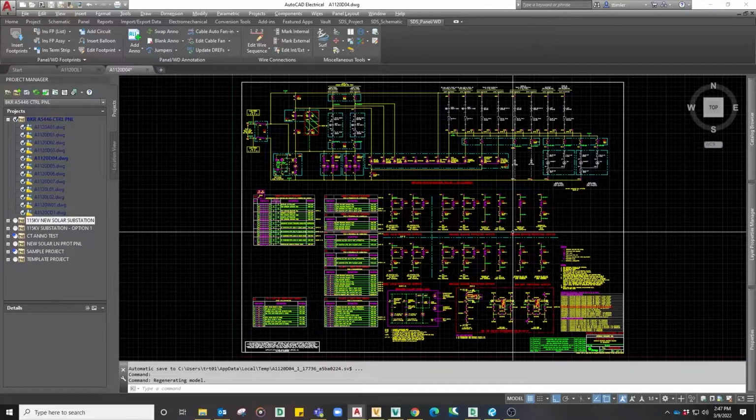All of these pre-wired protection outputs contain the master symbols that are used in conjunction with the SDS ref-only update tool in the SDS toolkit. You can find out more information on the SDS ref-only tool, master symbols, and reference-only symbols in the SDS help file located under the SDS Projects tab. Assigning master reference designations to symbols allows the lead designer to update all duplicate symbols referenced throughout the main substation project file during project updating.